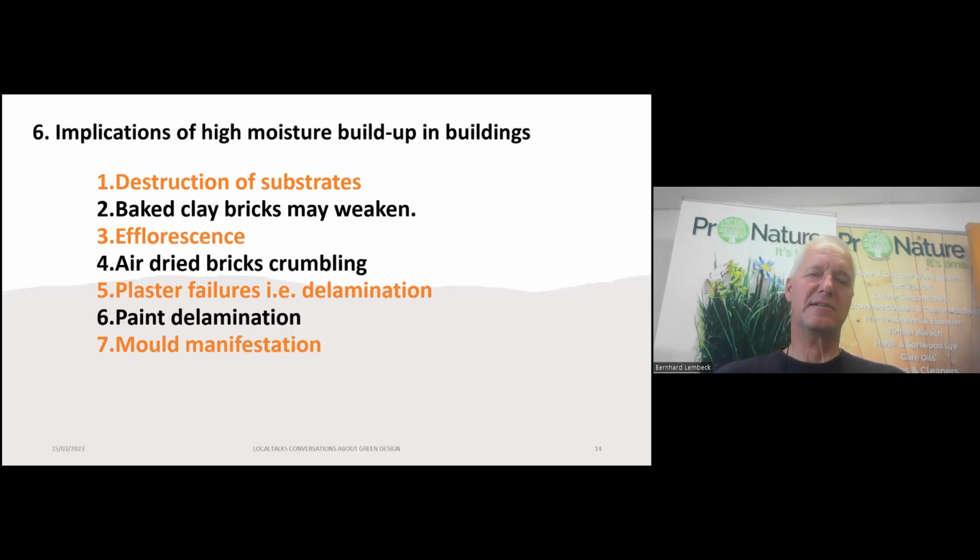Efflorescence is certainly a problem in bricked buildings, which probably is something that in a clay building would never be a problem. Air-dry bricks are crumbling. Plaster failures like delaminations or paint delamination, which is always a problem, and mold manifestation.